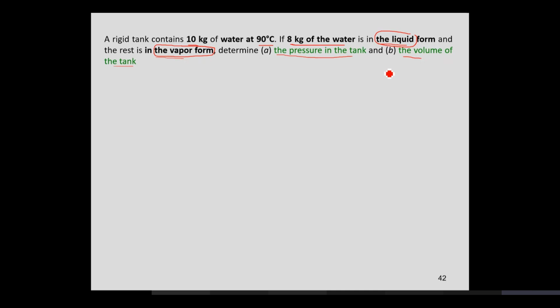If you remember, if I draw this, let's say a temperature specific volume plot. Number one, your system contains liquid. This is the compressed liquid state, this is the mixed state, and this is superheated vapor. Where do you have both of them coexisting together, liquid and vapors? The mixed state. It is the mixed state in which both of them are coexisting together.